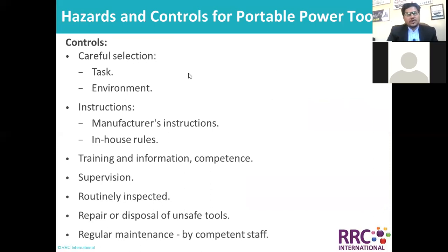And we require more effective controls against power tool risk, like careful selection as per the task and the environment. Make sure we are not ignoring the manufacturer's instructions or in-house rules, and training and information to ensure better competence. And yes, we require close supervision, routine inspection, repair or disposal of unsafe tools, and regular maintenance by competent staff.